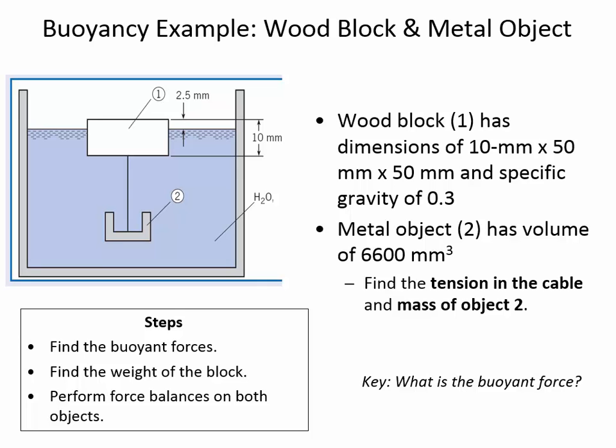And so we know that the hydrostatic forces are trying to open up that gate. So we've got water pushing this way. If this concrete block wasn't there to hold this hinge, then the hydrostatic forces would push this gate down and the water would just spill everywhere. But if we pull on this, then obviously it's causing a force to resist the hydrostatic force. So here's our hydrostatic force, F sub h. And you're going to have to find the magnitude of the hydrostatic force and its location, YCP, and do a moment analysis about the hinge.